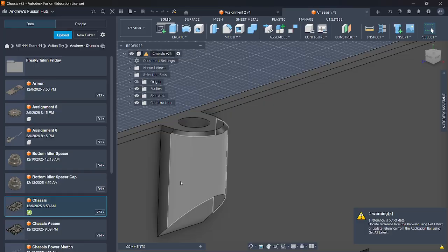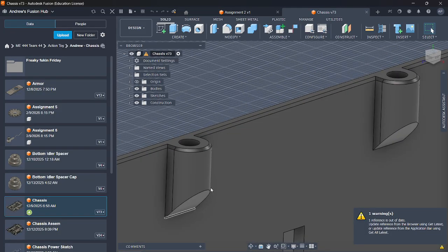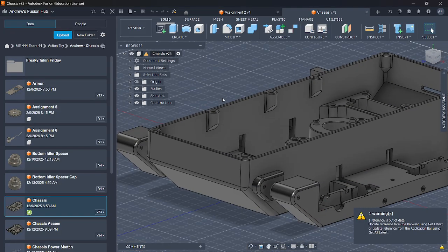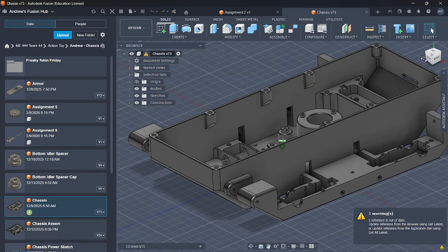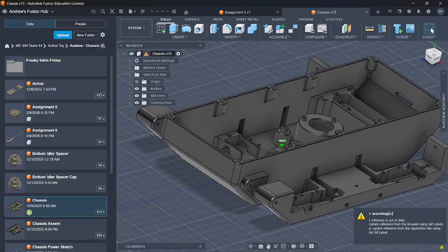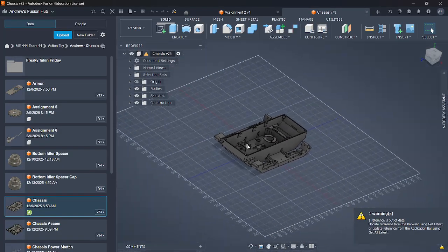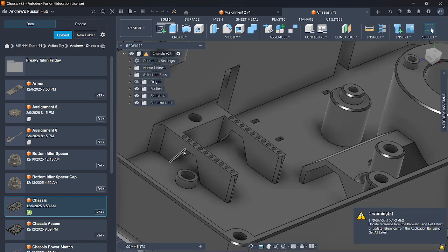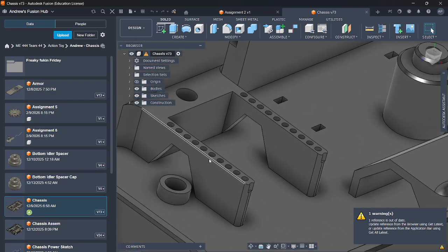You can see here, I have these jutting out at a 45-degree angle. So a lot of these things can be accounted for when 3D printing. Here, I made it go 45 and then I had a bridge. I could have gone straight up and across, but then going at this angle reduces that bridge length.